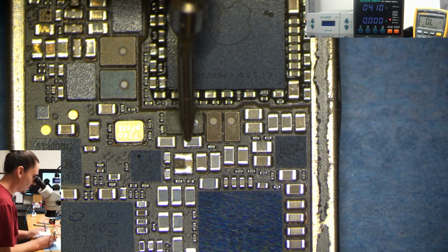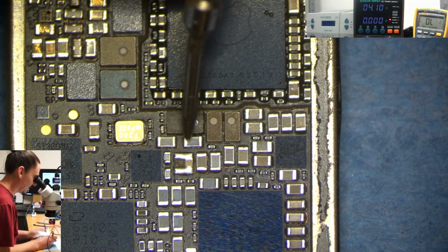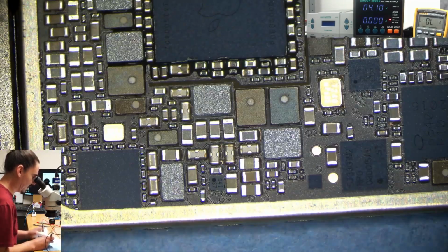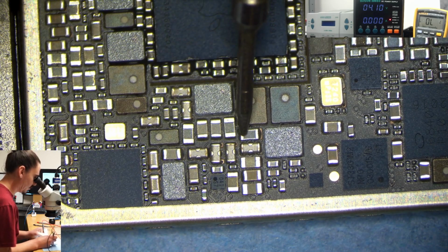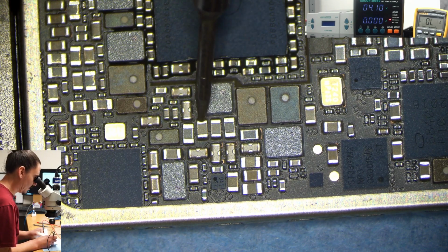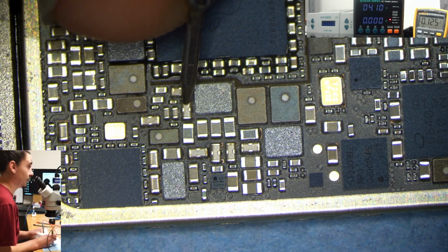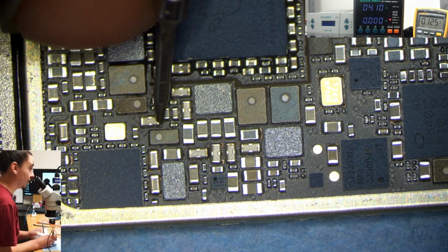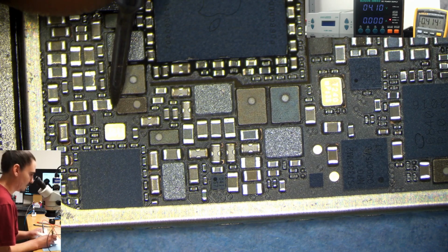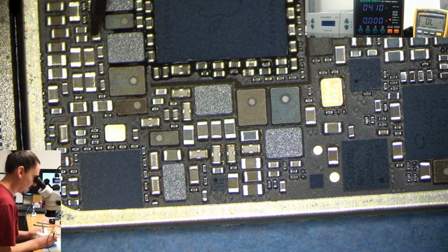These all look good so far. I can kind of see the pathways of where this coil leads to that connects to these capacitors. So I don't necessarily have to keep looking at my board view. Some of these are going to be low resistance lines, so they'll beep even though they're not necessarily short. I haven't found one yet, but you'll know it when I measure it. Like, this is PPGPU, and it's very low resistance, so that 0.006, that's not actually short, that's normal on this line.